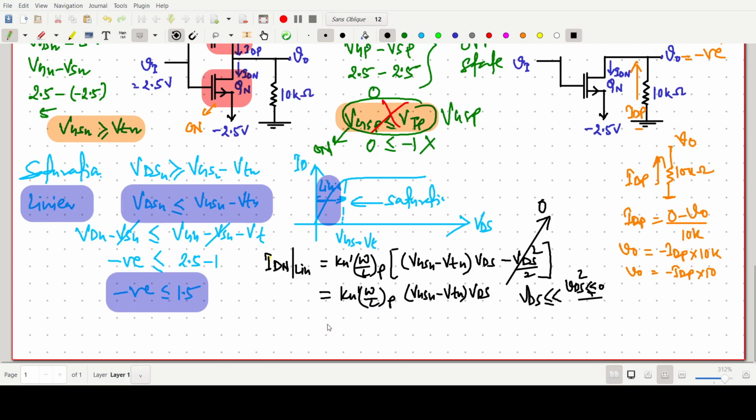Okay, so now what we can write, this one for the NMOS, so better to write n. So this one is 1 milliampere per volt squared: (VGn minus VSn minus VTn), and then (VDn minus VSn). We have to write the full equation. Now we have to put the values into the equation.